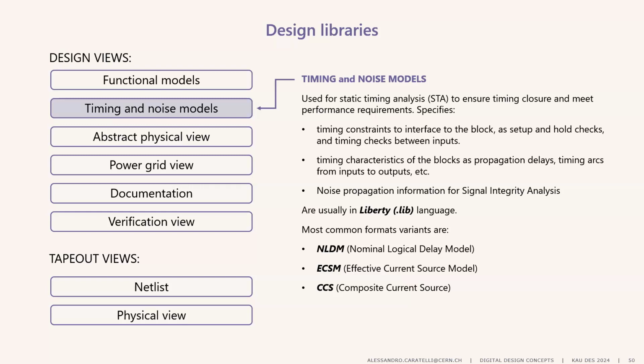These are usually given in a format called Liberty, which is a .lib file. It's a format, a language. The most common format variants are NLDM, ECSM, and CCS. I will not go more into the details. If you're interested, I can explain to you.